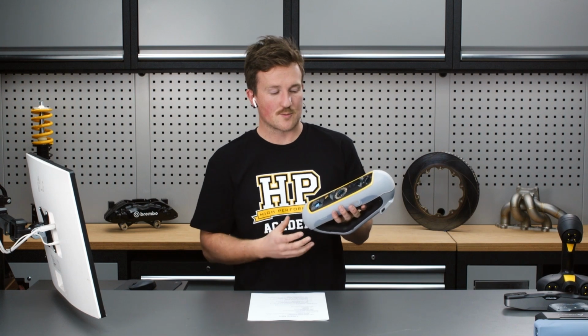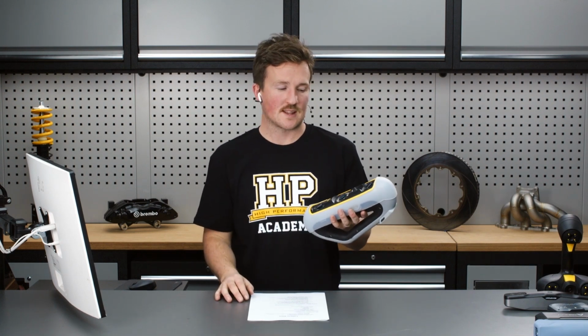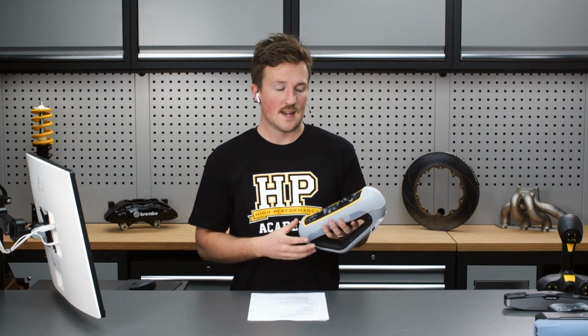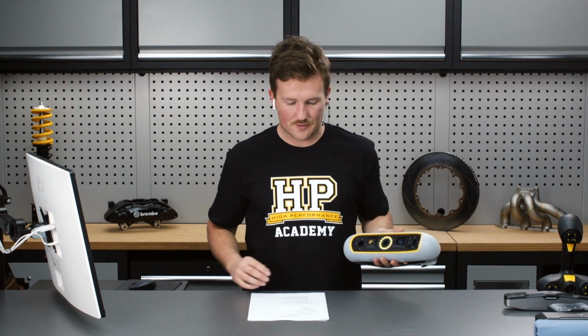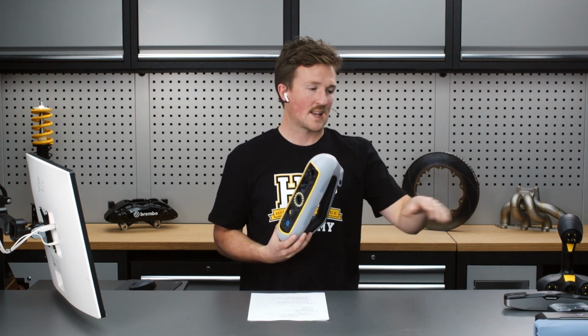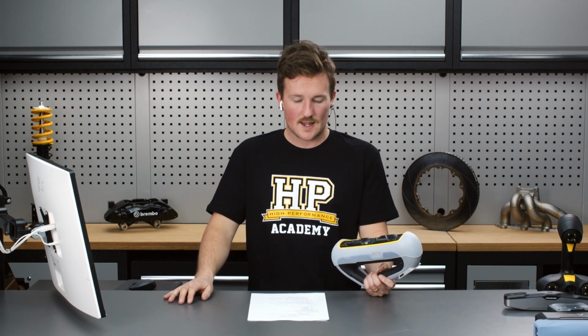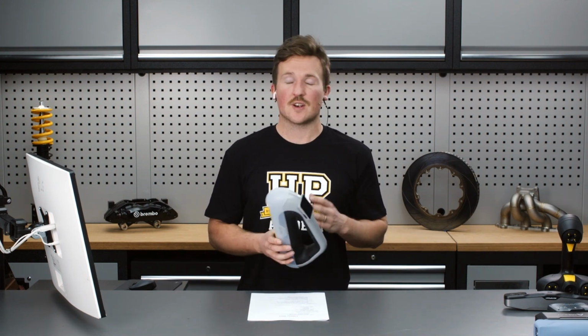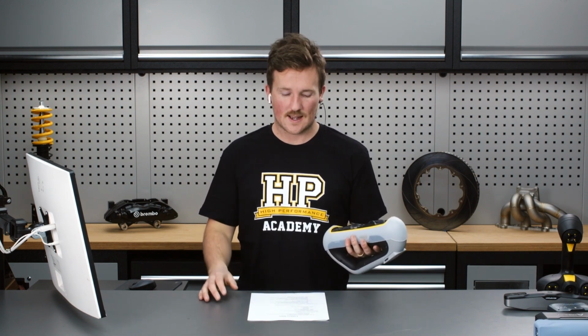You have that central projector and then two cameras receiving that information or viewing how that laser light lands on the surface. And that is very similar to structured light as well. So that's what these scanners all are here. And it's typically what's used in most automotive applications at the more entry-level price point anyway, because structured light scanning allows us to capture data very easily and quite quickly as well.